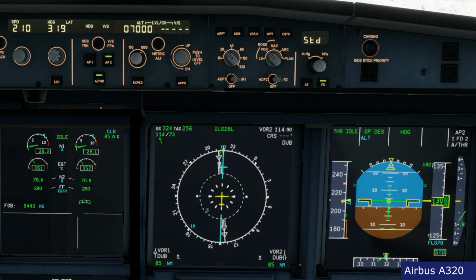There we go, we arrived at the selected speed, and you see the rate is increasing again, 900 feet per minute, 1000. That's more or less the rate we're going to keep, around 1100 feet per minute. That's at this speed, 210 knots. In clean configuration, that's more or less the rate that the aircraft maintains, 1000, 1200 feet per minute.